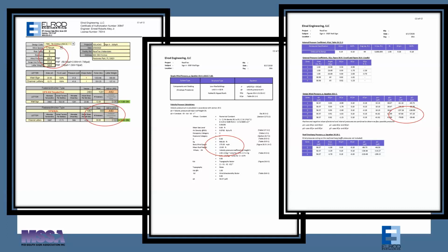We like to use red and green check boxes. Green boxes are good. You look at the slide on the middle, the center and the right screenshots are from the wind pressure analysis that we do. Again, you can kind of visually look at it, make sure that the proper wind speed for the area was used. And then if you look over to the right, we've mentioned a few minutes ago about the different zones on a building, zone 4 and zone 5.